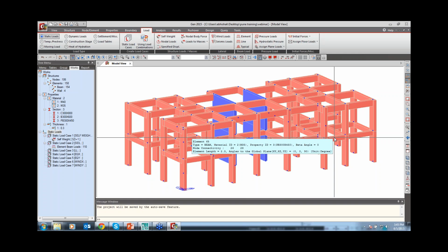And the beams are at say 3 meter center to center, but the wall should be 3.3 meter long. In this model the 3 meter long we are considering is your shear wall. If you want 3.3, you have to generate the beam according to the 3.3 meter length. Otherwise, we can break at particular nodes. Whatever exact length you want, you first have to generate that much length of beam, and according to that beam you can generate your wall.